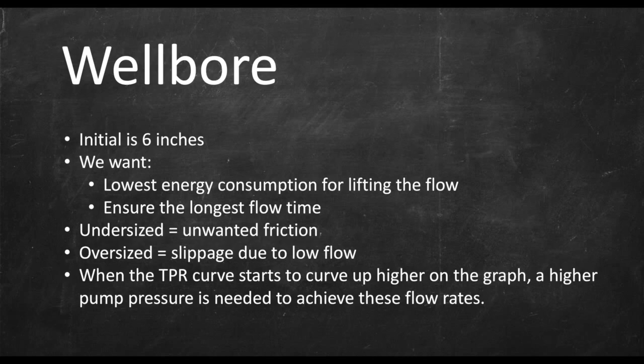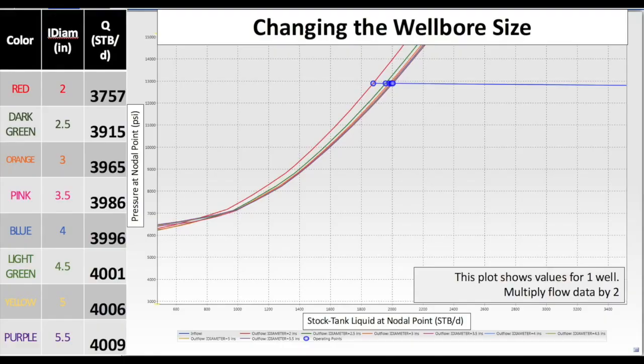When considering the effects of changing wellbore radius in Pipesim, we opted to delete our tubing and use the casing diameter as the changing wellbore radius. We had to use this workaround method because Pipesim would not give us the option to just change our wellbore radius. For our results, we tested 8 smaller inner diameters of the wellbore radius.